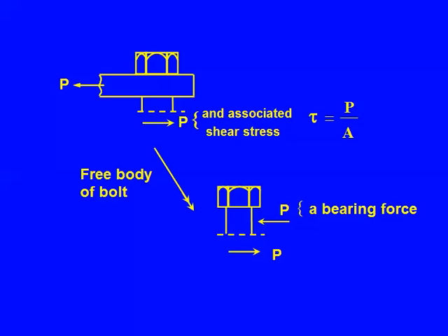We call it whatever you want. We call it a shear force. That's the bolt in shear. And if you, for some reason, wanted it in stress terms, you would divide it by the cross-sectional area of the bolt and get a kind of average figure. If you're doing LRFD, then you don't need stress, and if you're doing allowable stress design, then you need stress.